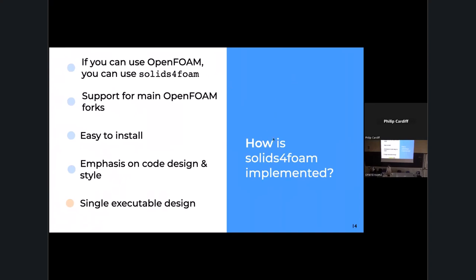So that's why. Now, how is solids4foam implemented? The ethos or the approach is: if you can use OpenFOAM, you can use solids4foam. So it's just an OpenFOAM case. It's just an OpenFOAM solver. The physics may be different, which you have to understand, but that's essentially it. There's an aim to support the main forks of OpenFOAM. That doesn't mean every version, but at least the main forks. It should be relatively easy to install. And I tried to place an emphasis on code design and style as well.